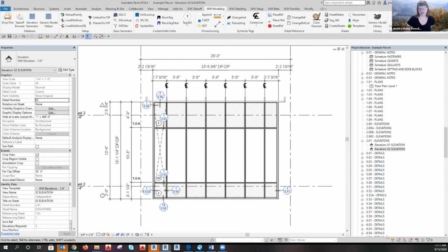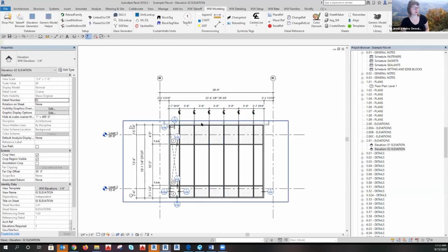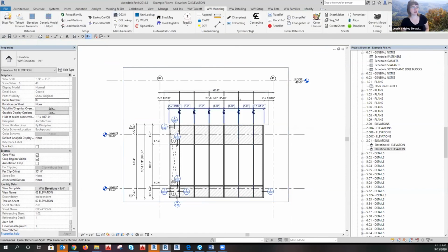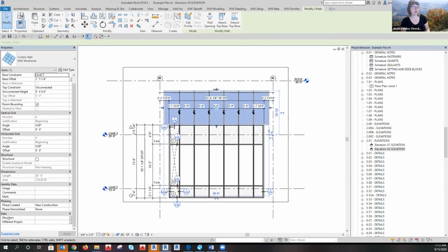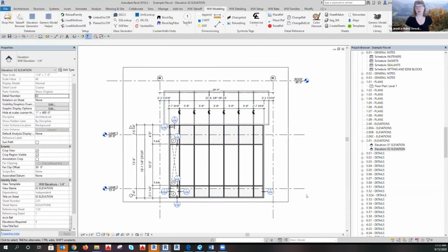Suppose in this case we had two curtain walls, one above the other, and both are in one elevation. If we have two separate walls on one elevation, we have to give the same number. Don't forget. Yep, that's a really good point. We've kind of done this wrong on purpose because we were running out of time, but really you would have to manually adjust all these dimensions. Once you've exported this top piece, you'd have to make sure that the elevation data is 02 and matches exactly the other elevation it belongs to.